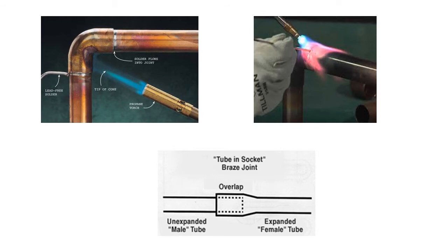Soldered connections with fittings are used in plumbing for domestic water lines, and in heating for supply and return lines in a forced hot water system. Braze connections are used when greater connection strength is required or when service temperatures are as high as 350 degrees Fahrenheit. Brazing is preferred and often required for connections in the air conditioning and refrigeration field.